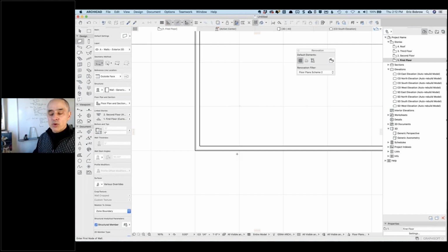Now, how useful or important that is, I don't know, but certainly sometimes it's nice to just have things snap and line up, etc. So the set rotated grid allows you to move the grid start point as well as, if you want, to rotate it. The origin of the snap grid is set by the set user origin, but the origin of the visual grid is set by the set rotated grid option. Okay.